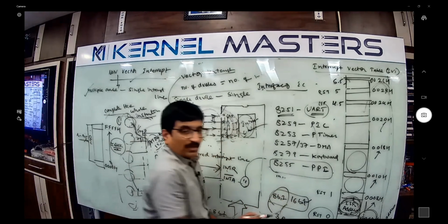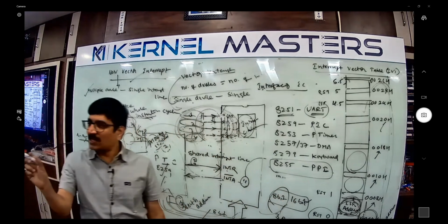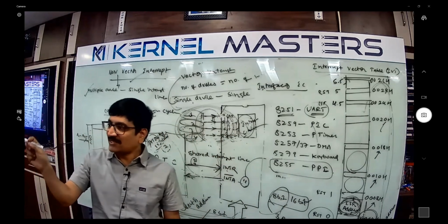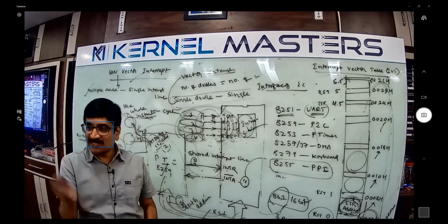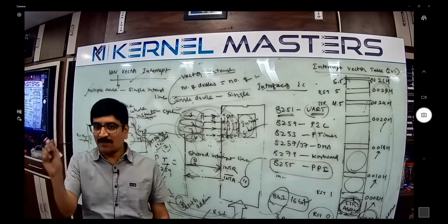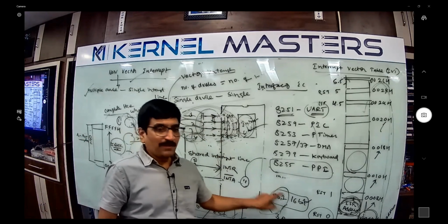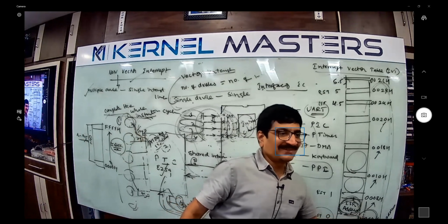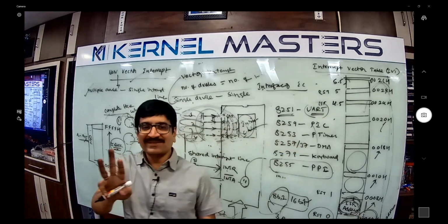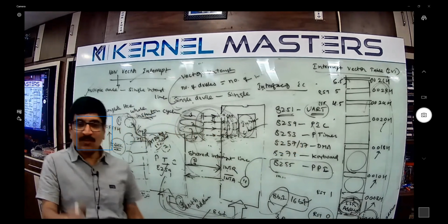The instruction also has the opcode. The mnemonic is Call. Microprocessor understands the call, no? Call is 1 byte. The remaining 2 bytes are what? Address. Total how many bytes? 3 bytes. So now, but actually the bus width is 8 bits.